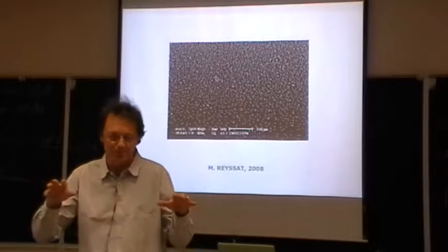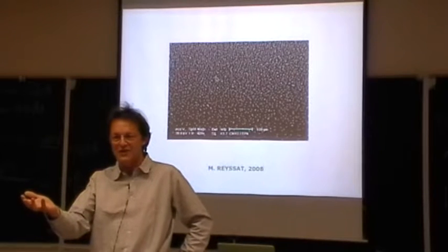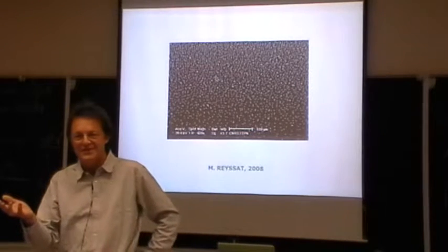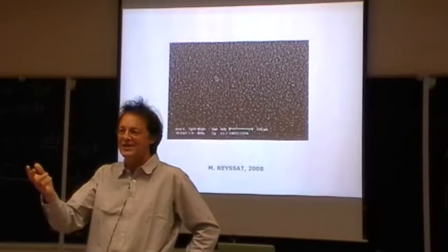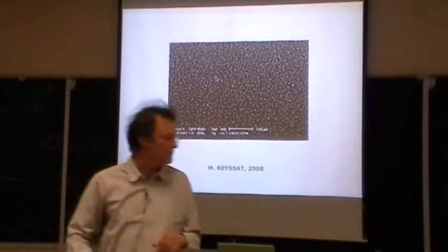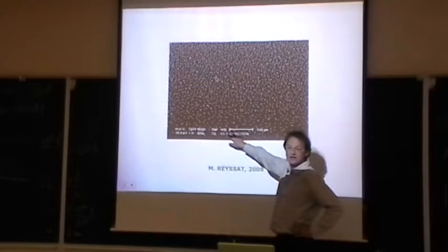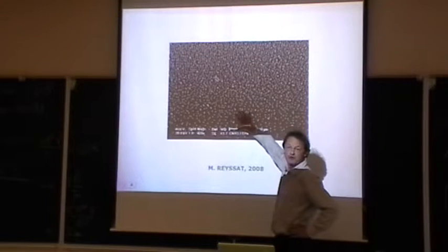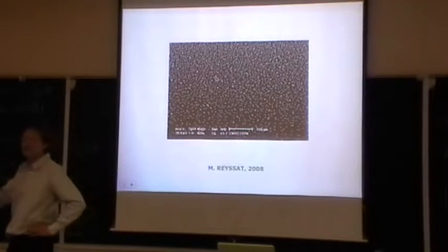And we saw that the principle is that if the texture is hydrophobic, then this tends to detach the liquid from the surface. And of course, the larger the density of pillars, the less hydrophobic it is, because hydrophobicity is a function of the quantity of air which is below. So if you have a region where you have a very small density of pillars, which is the case here, the pillars are very small because the scale here is very large. Below a drop that you put here, there is mainly air, 99% of air and 1% of pillar, while at the top you have 10% of pillars, so you have only 90% of air.